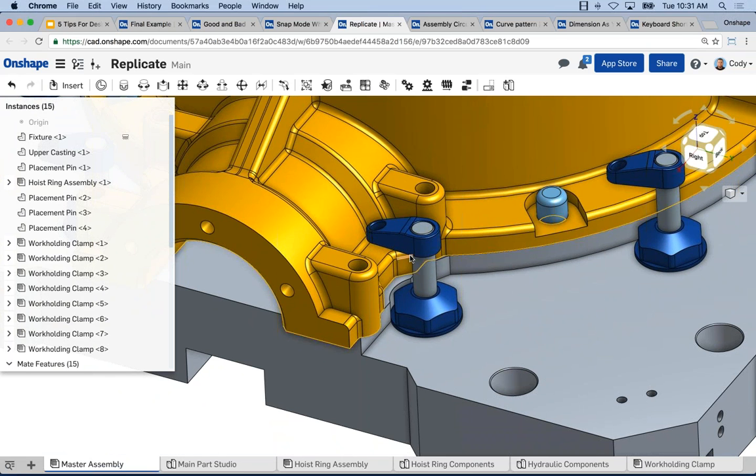You could easily define it with a different mate that didn't allow it to rotate, and then I can set the exact angle by editing the mate connector. So just keep in mind, this is free to rotate, and it's free to move up and down and rotate. That's deliberate. That's because the design needs to be able to do that. But I can easily, in the subassembly, say, no, this should only move up and down, not spin, for example.